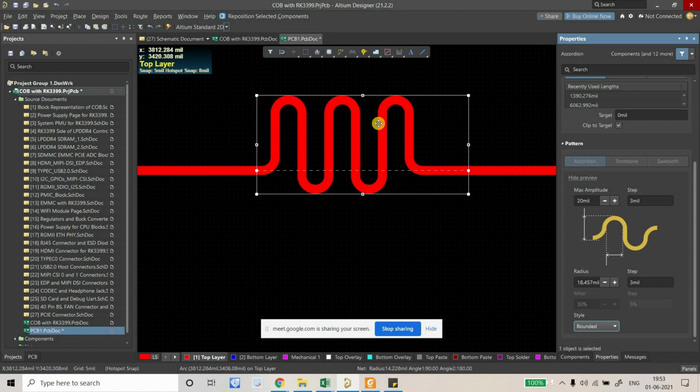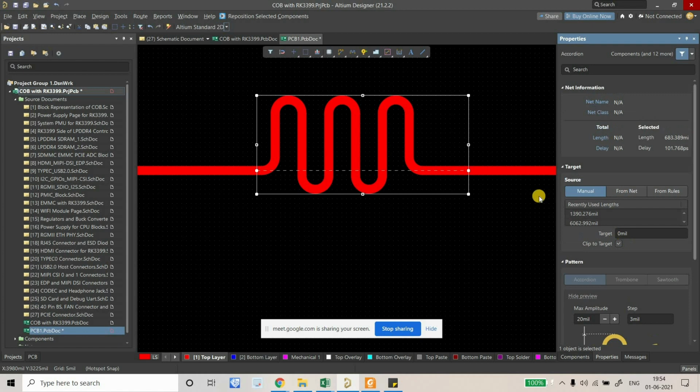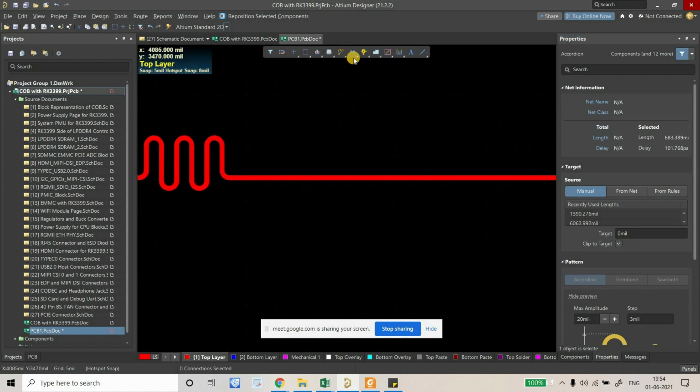Another thing is that it's very fine, whatever the consideration was related to impedance. So according to that, this would be the perfect option, right? But one more disadvantage of using this round option is that it takes a lot of area to route the connection, because it's a semicircle on the edges. So it takes a lot of space. When you have to length match, you need a lot of area for routing these kinds of serpentine. You're getting it? Okay, let's talk about another one.